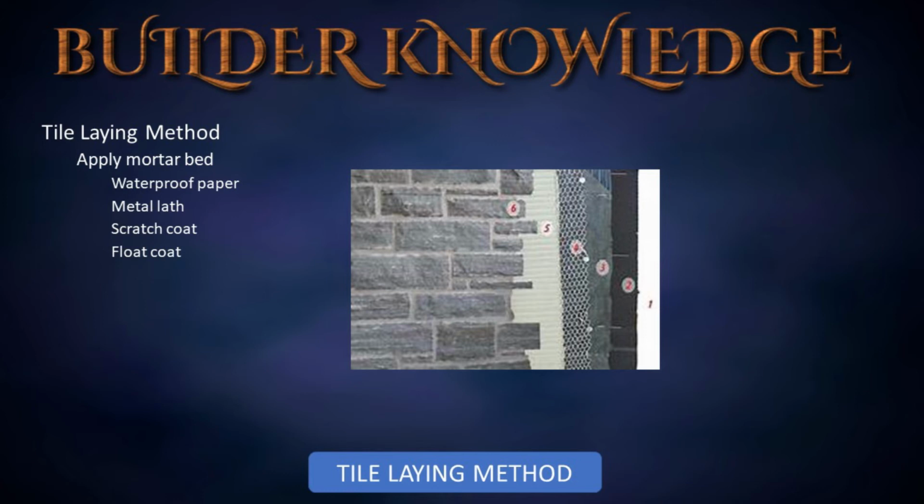Keep scratch coat protected and moist during the hydration period. Set tiles no sooner than 24 hours after applying scratch coat, but no longer than 48 hours after applying scratch coat.